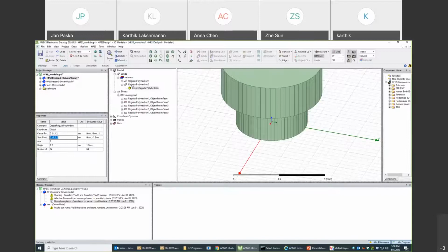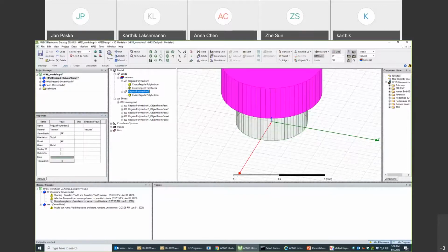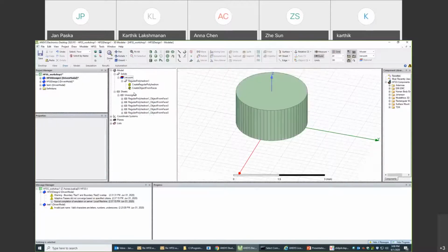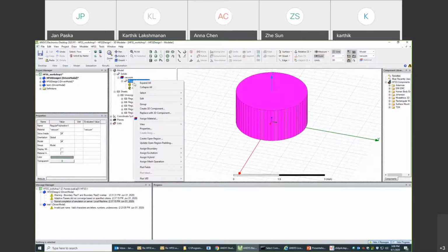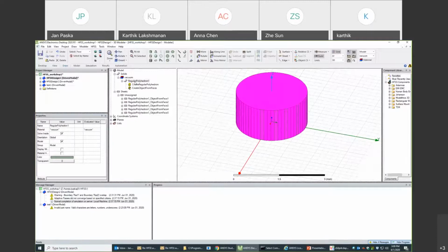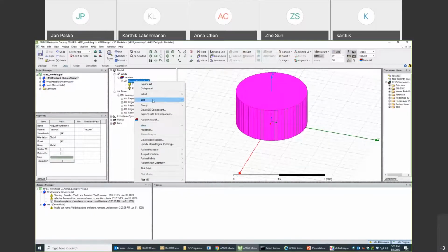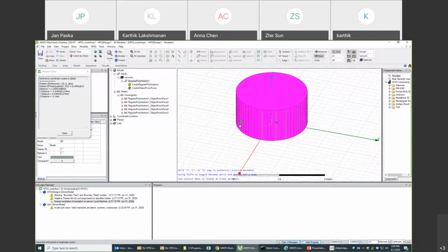But what is it bigger? I see what you're doing. Okay, yeah. Actually, it's easier to just move it. Let's delete this. Let's move this. Edit, arrange, move. Not arrange, but edit, duplicate along line. 0, 0, 0, and then 1.2, right?